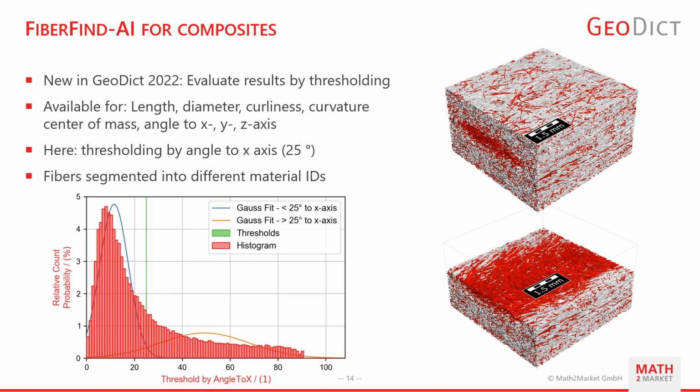And again, it is confirmed what we also saw in the diagram, that in the center area, probably caused by the manufacturing process of this material, we have a kind of change in the fiber orientation. And depending on whether you want this kind of change in the orientation or not, you can now better understand why your material maybe performs or does not perform as expected.